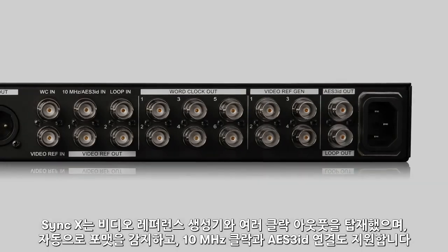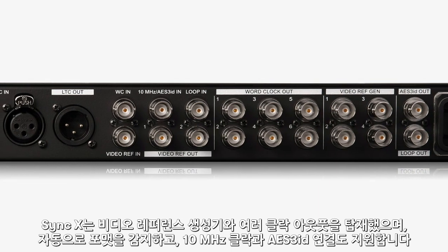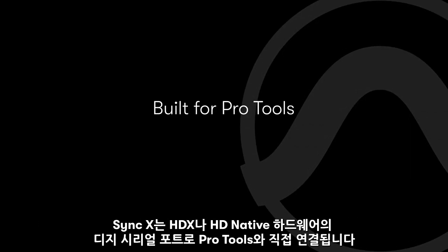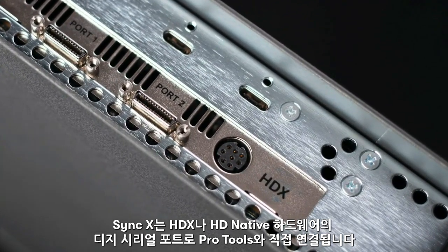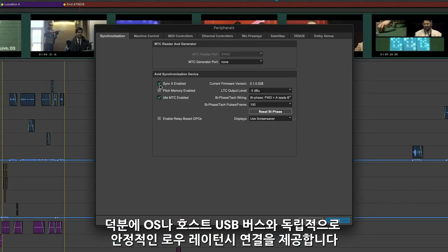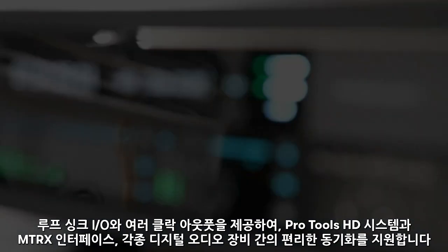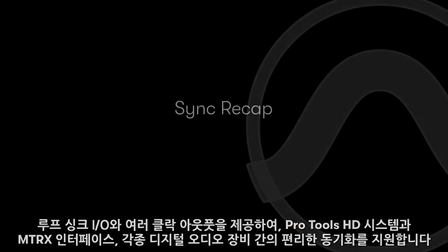Sync X expands on the features of the Sync HD, with a built-in video reference generator, multiple reference and clock outputs, automatic video reference format detection, and support for 10 MHz clock and AES-3 ID. Sync X connects directly to Pro Tools via the Digi serial port found on HDX and HD native hardware. This provides a reliable low-latency connection that's independent of the OS and host USB buses. Support for loop sync is maintained, which is used on the HD series Pro Tools interfaces, while the multiple word clock outputs provide connection for MTRX interfaces and most other digital audio equipment.